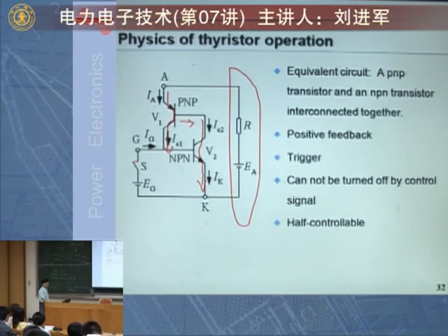Okay, from the emitter to the collector. Okay, when you generate this current, remember this current is also injecting into the base of V2. So that current is also generating additional base current for V2. That will make V2 generate even larger collector and emitter current.